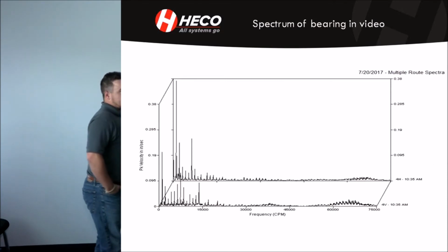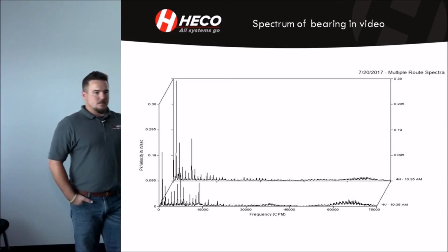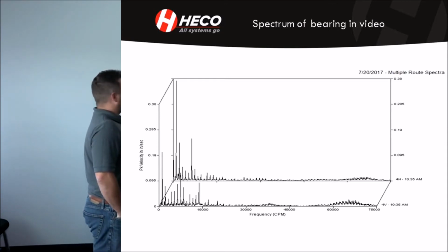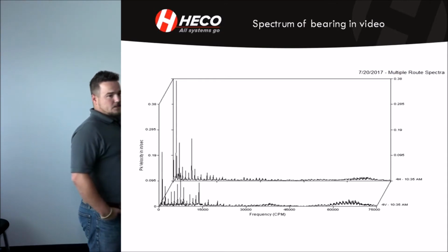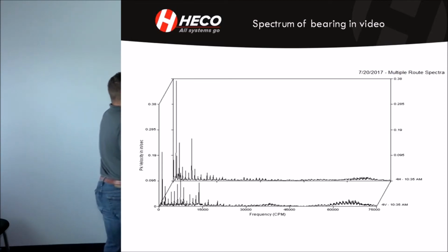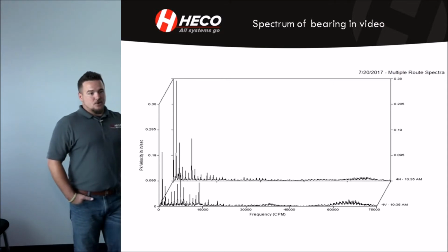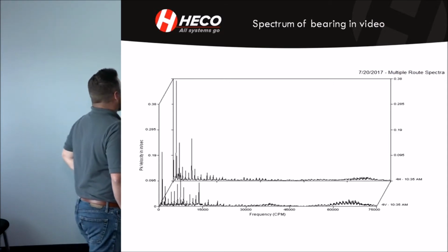Normally, when you have a bearing that has problems, it's one of those things we talked about for the internal wear, it would have a non-synchronous pattern and maybe some of this floor noise, but that's only at real high stages of failure. This is all 1 times the fan shaft speed with harmonics and floor noise, so it basically is showing extreme looseness or mechanical looseness.